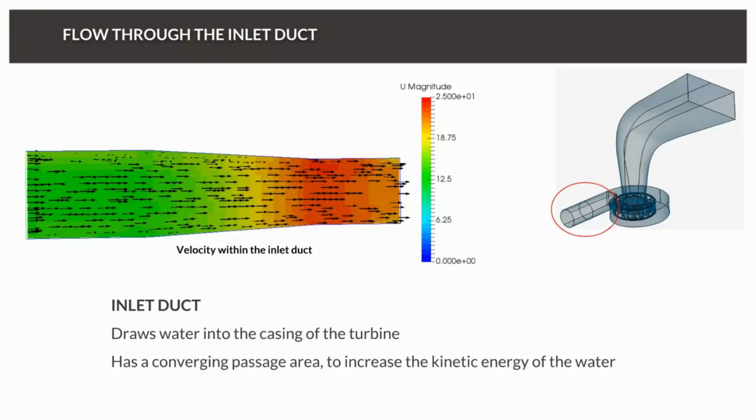We can see that that is happening here. But again, what we don't know, and what we could find out easily with SimScale, is what would happen if we changed the diameter here, right? And would it improve our design or would it make it worse? So we could make a quick geometry change in CAD, upload it again to the SimScale platform, utilize the same simulation setups, and then compare the results again side by side.